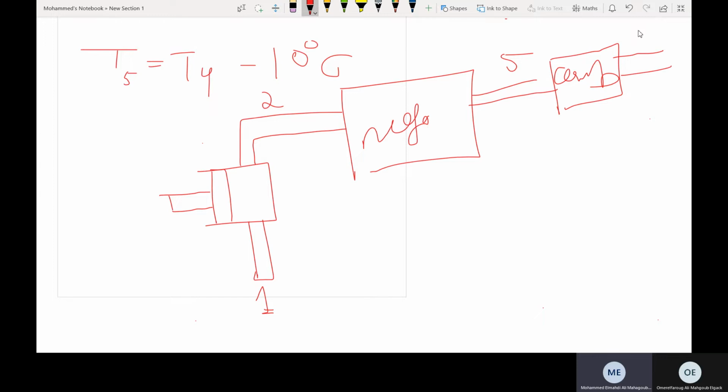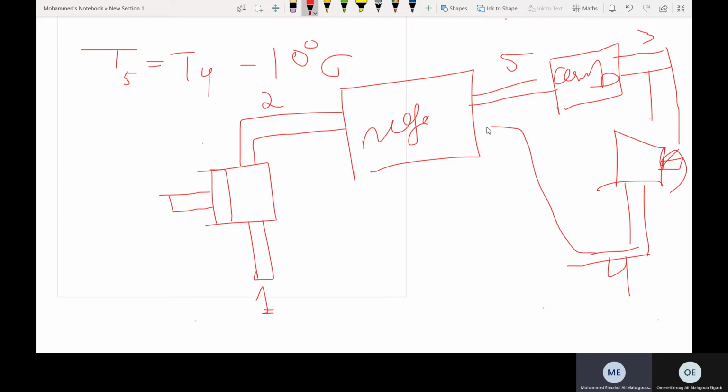This is point 3 here after the combustion happens, and then we go to the turbine, of course. We generate our work here, and then this is point 4, and then the outlet here, point 4, is going to enter the regenerator, and then leave as point 6. Leave the regenerator, and then from 6 here we can go to point 1. Maybe it's going to exhaust to the air. It's going to mix with the environment air to go back again to point 1.